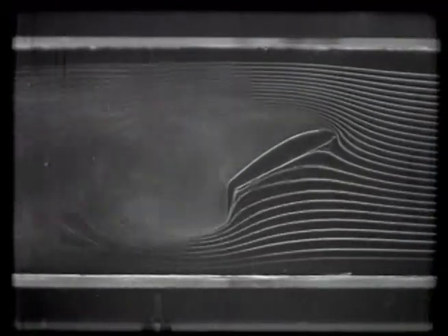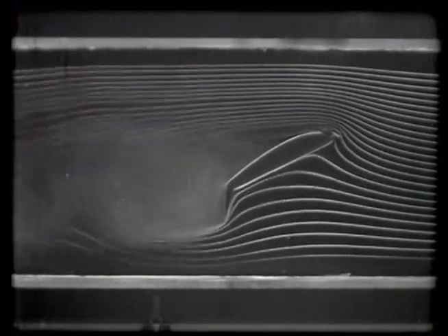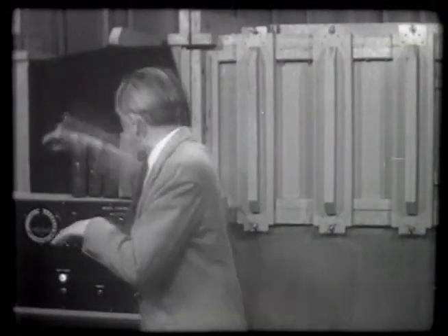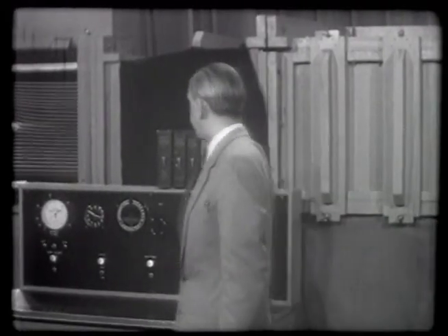Here, once more. Now you can make this go automatically, and in this way you can even prevent any dangerous situation even if the pilot is not able to think about it. But the trouble with the slotted wing is this, that due to all this machinery which you need, you have quite a bit of drag on it. And it causes more drag than a smooth wing, which is obvious.